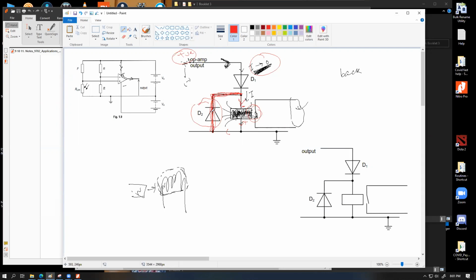Now, if we do not provide this diode, if there was only a single piece of wire, you have to understand this thing. Current starts to flow through here. It is flowing through the diode without obstruction. Whenever it reaches this junction, it has two alternative pathways. It can either flow through a single piece of wire, let's say if this diode did not exist, then this would be a single piece of wire, or it would have to flow through the solenoid. Essentially, the current would necessarily try to flow through the single piece of wire, so the current would not go through the solenoid. We want the current to go through the solenoid and the back EMF to flow through this way. That's where this diode comes in. This diode would not allow the downward current to flow through this way.